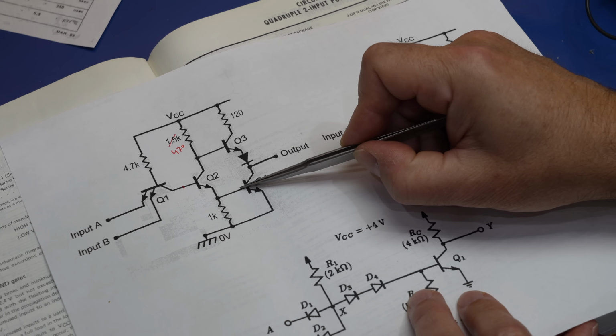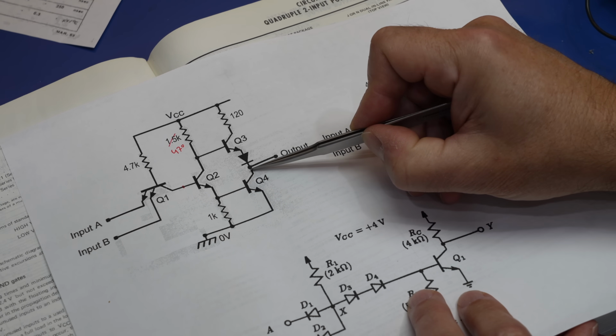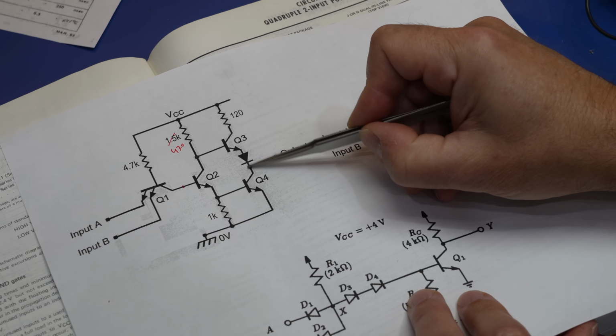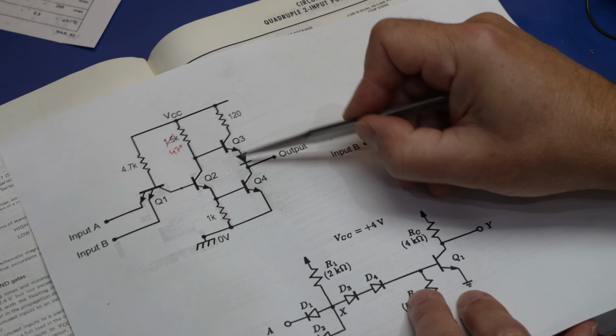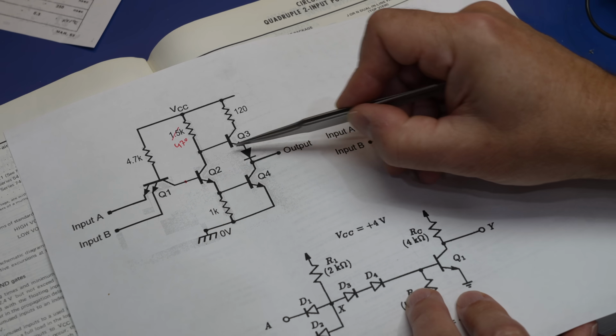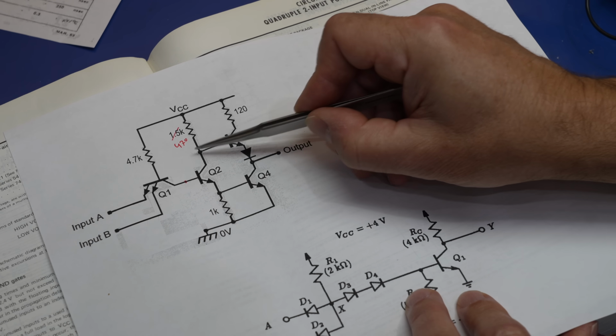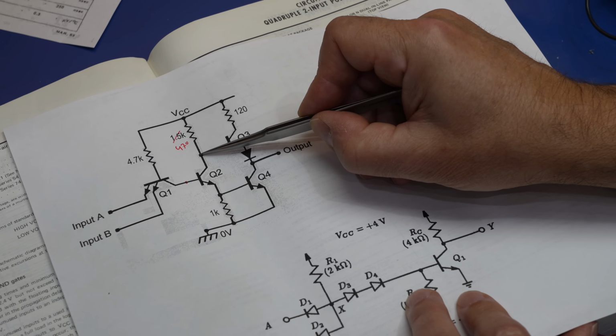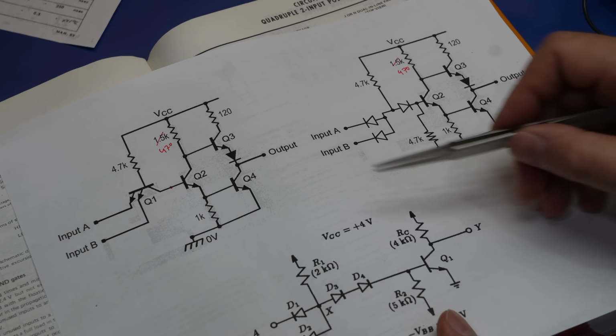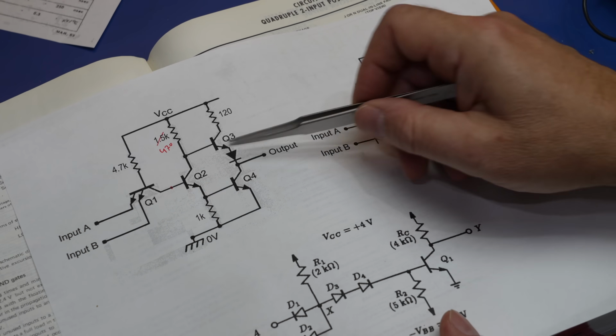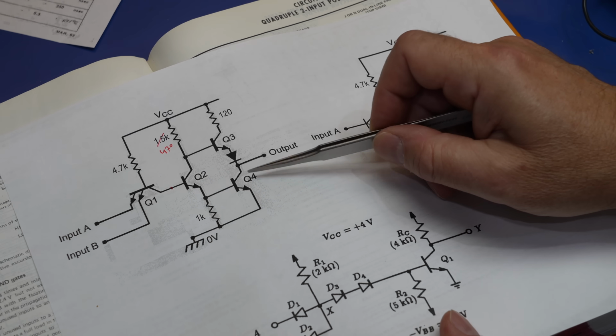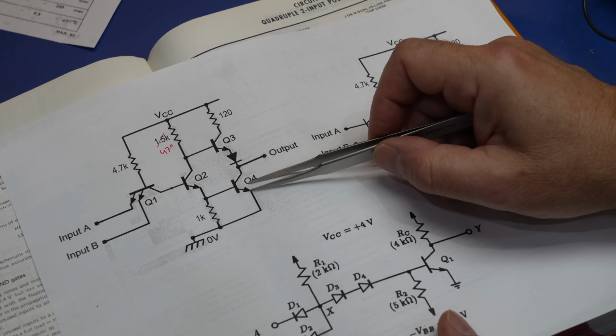So for a while it's conducting, and what I am seeing here is the transistor still conducting, and it's bringing down the voltage through Q3 at the collector. Well, first, why is it happening in this gate? Because I used the wrong transistor. So this was all optimized for the transistor they had. Mine are way bigger, they have way more capacitance.